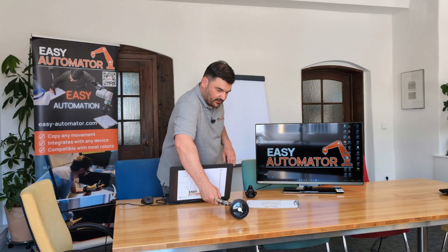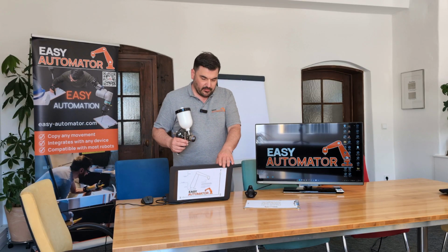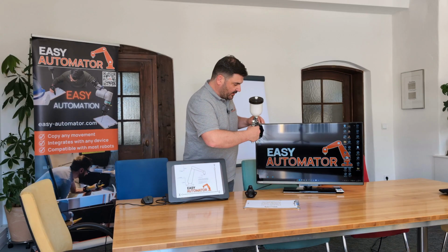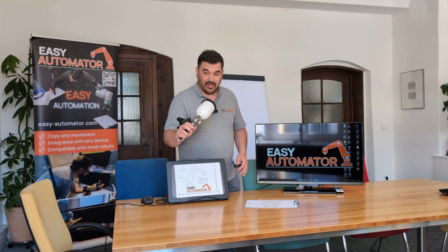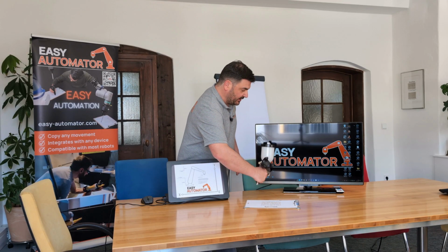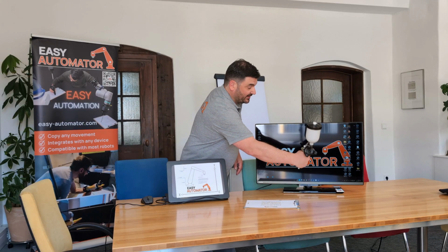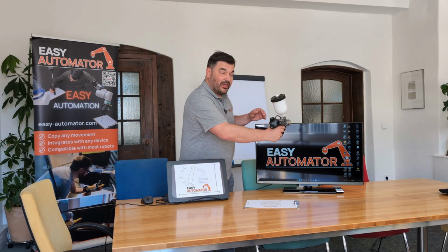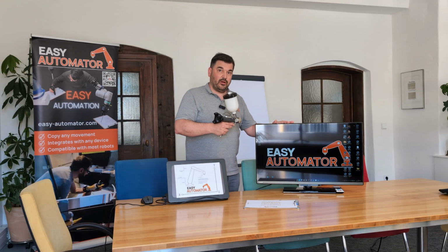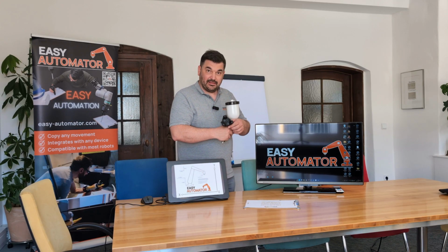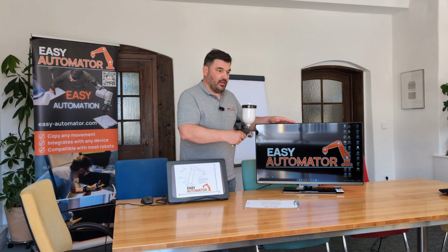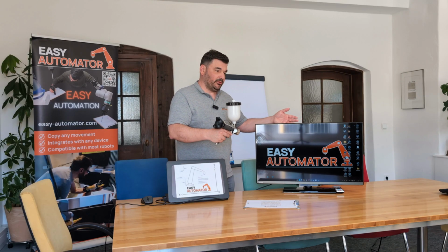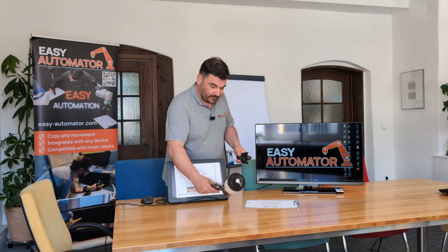Why do we need this? For coating, for grinding, for any manufacturing purposes, customers are integrating the teach pen to the manual device they have for manual processing, and then they just do all the processing technically correct, exactly the same way as they would do every day for the tasks. As a next step, you can create a robot program, and after the first mimic and teaching, the robot will take over and continue to complete the task with the rest of the workpieces for you.